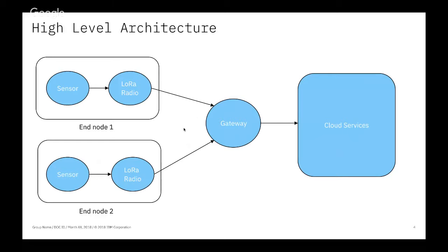Essentially, this is because we're able to enable sensors to send data at a long range, all while using minimal battery. One of the main drawbacks is the limited bandwidth, because you can't really send larger data formats like pictures and audio. But in this situation, we'll mostly just be sending sensor data as small text packets, for example accelerometer data, location, temperature, etc. So bandwidth shouldn't be a concern.